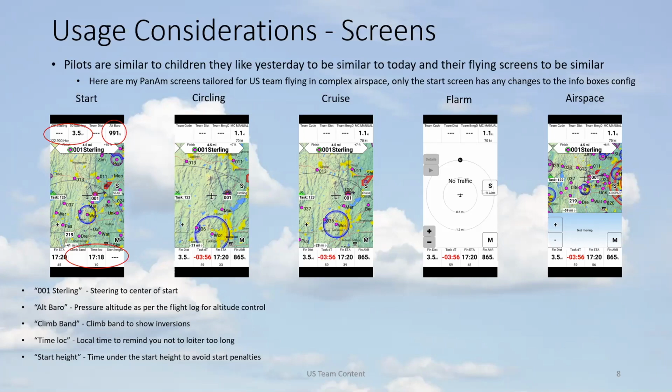So that's another key thing from my perspective when you're using these flight computers: keep it as simple as possible, such that when you get into duress, you have a go-to location on the screen to get the information you want. You're not having to read these little titles, because every screen's got a different piece of information on it. That's too error prone when you're in a stressful situation.